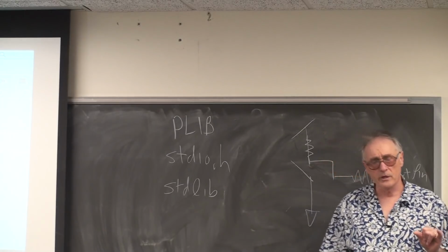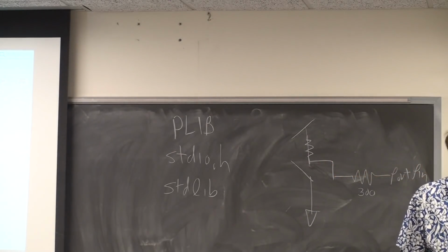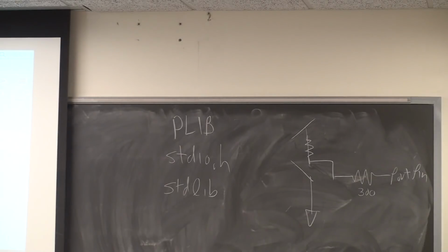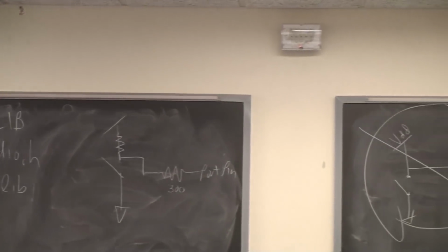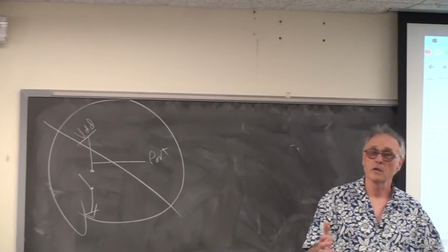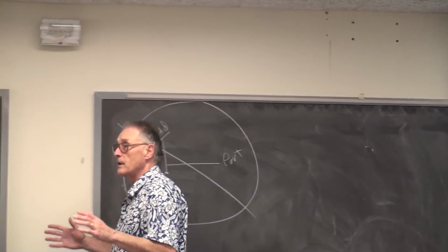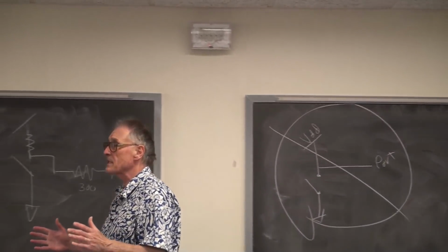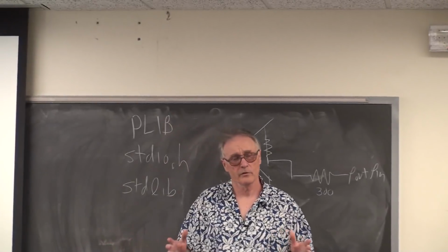To make things more interesting, there's 128K of flash, which was where you'd normally put program code. However, if you have a large static array that never changes, let's say it's a lookup table of exponentials or sines and cosines, you could put those tables that you never write into flash and save RAM. I'll show you how to do that.